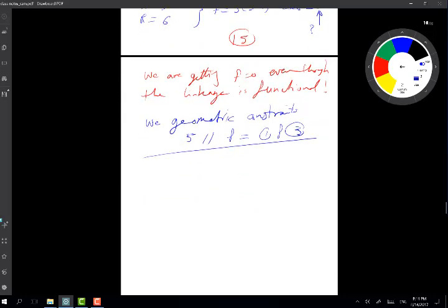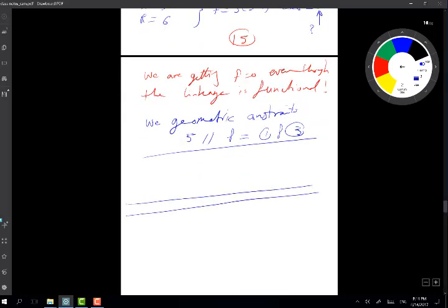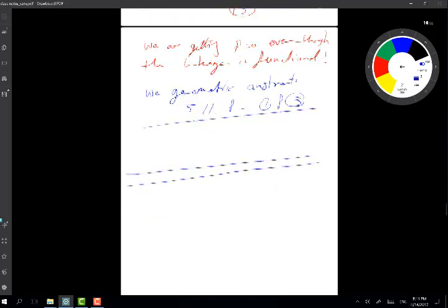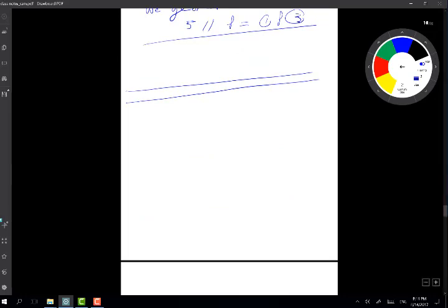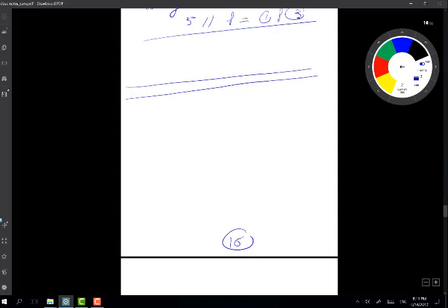So these calculations we do for degrees of freedom are very useful because in most cases they give us straightforward answers about what's happening, the number of motors, and so on. But occasionally they give us numbers we don't expect. At this point, it's an opportunity for us to stop for a second and think about what extra constraints I have to deal with here to ensure motion is going to happen, and so on, right?